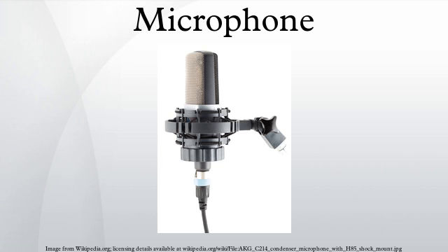A more comprehensive standard for the description of measurement microphone performance was recently adopted. Measurement microphones are generally scalar sensors of pressure. They exhibit an omnidirectional response, limited only by the scattering profile of their physical dimensions. Sound intensity or sound power measurements require pressure gradient measurements, which are typically made using arrays of at least 2 microphones, or with hot wire anemometers.